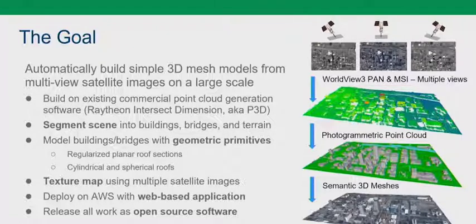As part of that texturing process, we also want to improve the texture. When you take pictures from satellites, shadows are an issue, so we want to deal with shadows and remove them. One of the techniques we use is to render the scene effectively from the sun's point of view and figure out where the shadows would be in the images, and then not use those to texture the final model. That's how you get this really pretty view with no shadows that you can then post-process to light any way you'd like.